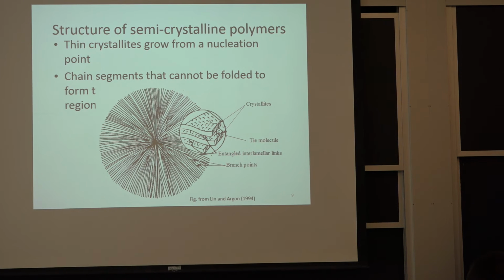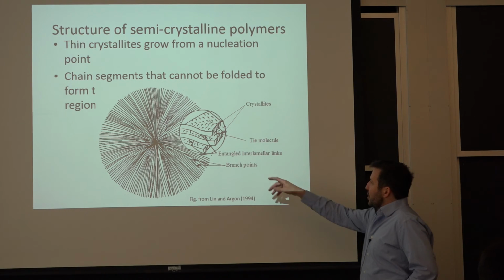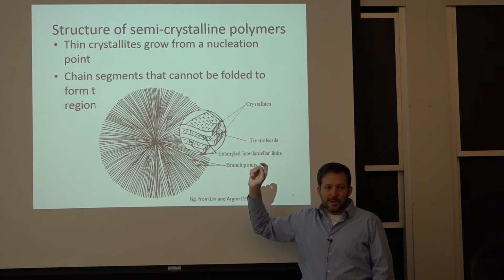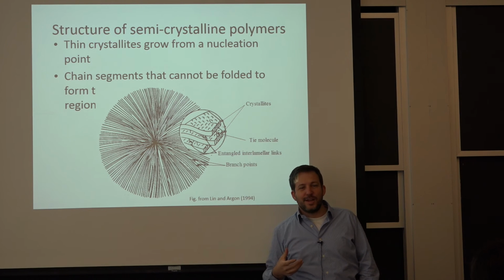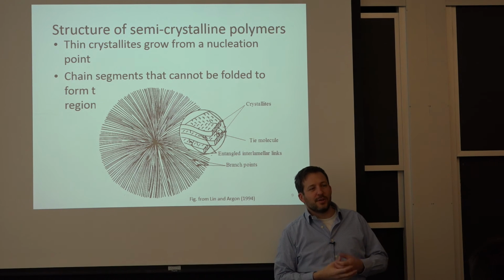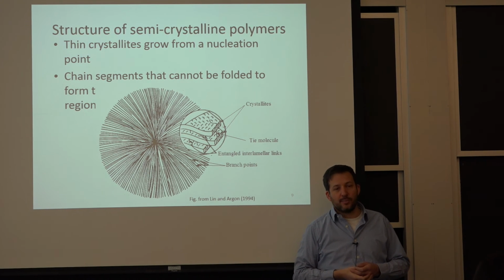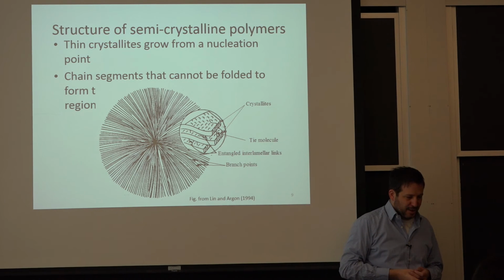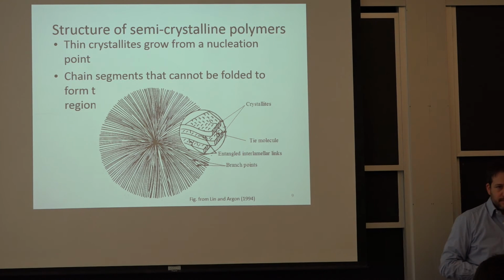And that's why the polymer gets a lot stronger when it starts to crystallize, because now it's a composite at the microscale. These organized zones essentially have lower energy, but you can't crystallize the whole thing because all these other interactions are stopping you from forming a complete large crystal.